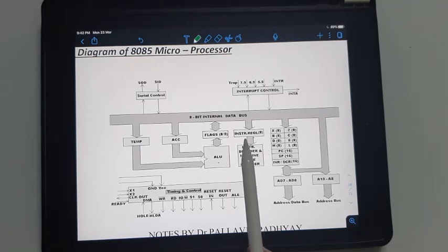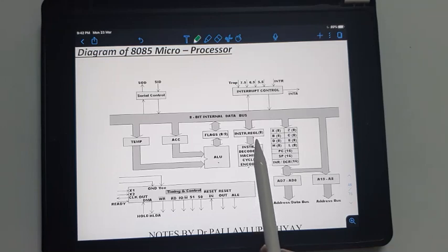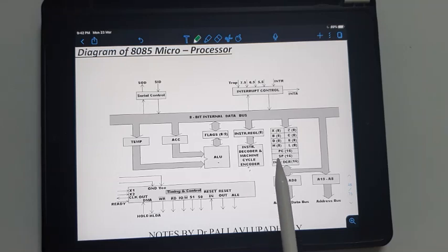It's an 8-bit register, and from it the instruction will go into an instruction decoder, which will decode the instruction, and then machine cycles will be executed for this particular instruction. When all the machine cycles finish, that means this instruction has been executed. Now another instruction is required to be brought in.